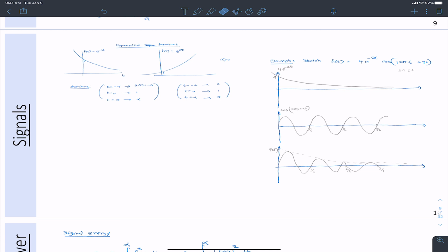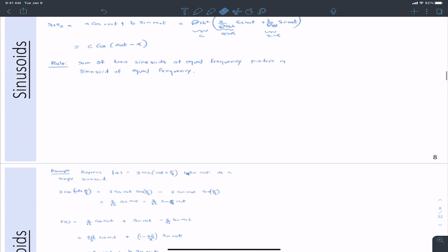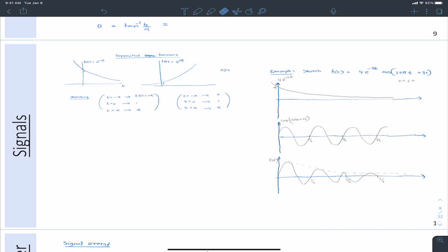In the last lecture, we stopped with looking at a sinusoidal signal. Today we are going to start with another type of signal, the exponential signal. Usually we write an exponential signal as f(t) equals e to the power at, or e to the power minus at. Let's start with e to the power minus at. So let's plot this signal similar to how we plotted the sinusoid signal.